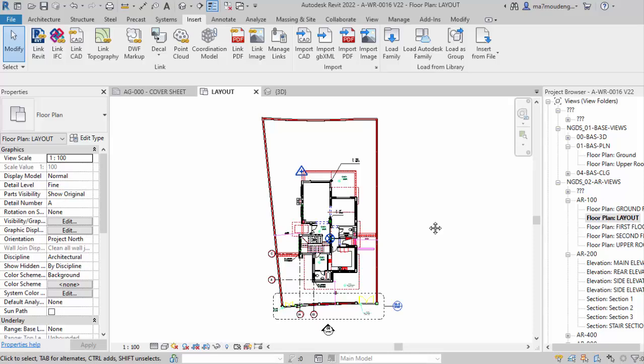And I'm sure that it's a bit confusing in Revit when we talk about the coordinate system. Somebody asked, where is the coordinate system in Revit and how can I set my coordinate system in the right way in Revit? And the easy answer for this is Revit has no coordinate system. You are the one who will decide the coordinate system according to your project.